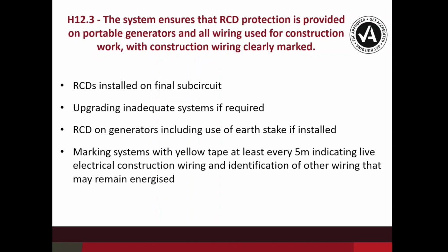RCD is a fairly simple approach to looking at electrical safety in terms of we have our milliseconds and our milliamps, and depending on the installation and the type, will determine what RCDs are required. When we go through that, it needs to be on the final subcircuit. So in other words, it's closest to the point where the operation will be required. It's usually on each temporary switchboard, which has its own RCD setup. We then go to having a look at upgrading systems if we don't have it. There are ways and means of using alternative boxes and things like that that give us our RCD protection. But the idea is that we have that protection, that it's tested.